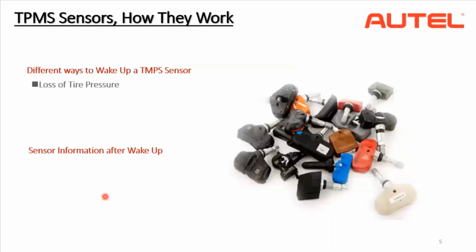Moving on. Now we will look more into TPMS sensors and how they transmit data to the vehicle's ECU. In order to transmit TPMS data, the TPMS sensor should be awake or active.